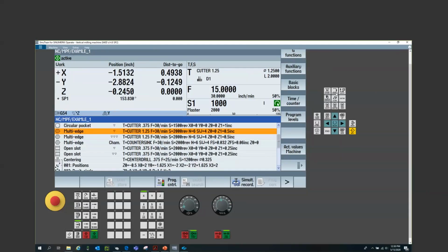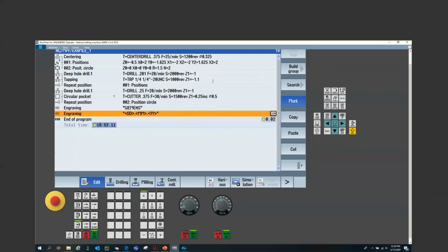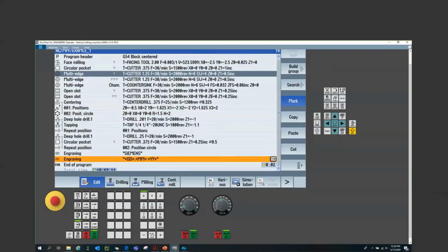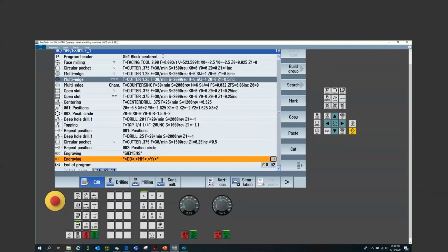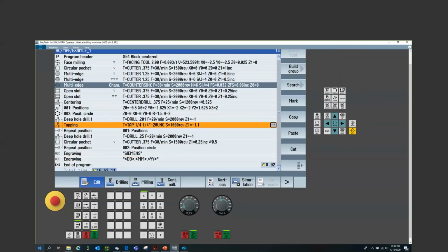One of the tricks with utilizing any G-code cycles in a conversational format like Steve was showing here is that in G-code, you have to do all your preparatory commands prior to getting into the cycle, right? You've got to do your tool changes, fire up your spindle. So you can get to all that stuff. Steve, you want to show them where you could do a tool change for argument's sake? If you just pick whatever line it is in the program where you wanted to execute that, press the enter